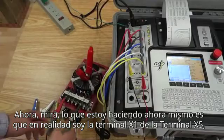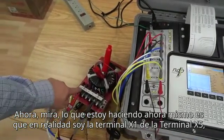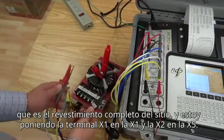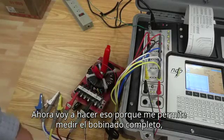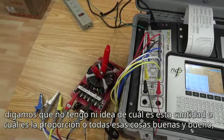Now, what I'm doing right now is I'm connecting the X1 terminal and the X5 terminal, which is the complete winding of the CT, putting X1 on X1 and the X2 terminal on X5. I'm going to do that because it allows me to measure the full winding.